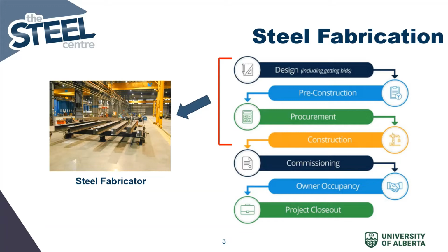For many steel fabricators, they'll have their own in-house engineering team that will be responsible for designing the connections for that specific structure. And it's really the connections that dictate what a lot of the steel comes out to become during the fabrication process. So in the connection design, it's important to consider a lot of these different factors in the fabrication process in order to try to optimize and minimize the cost of fabrication itself.